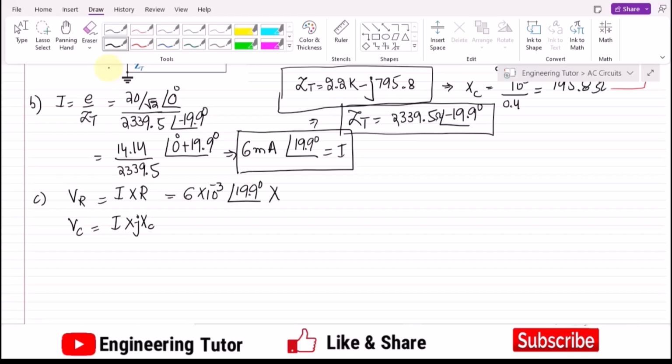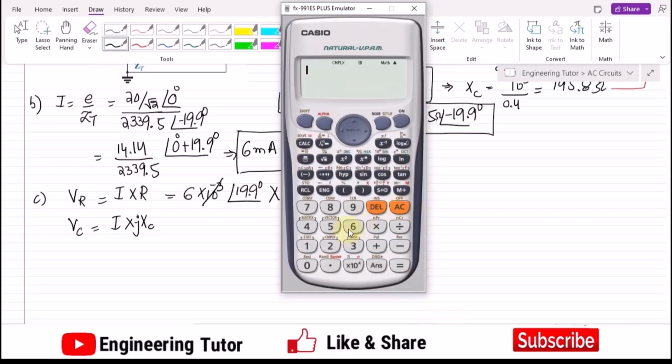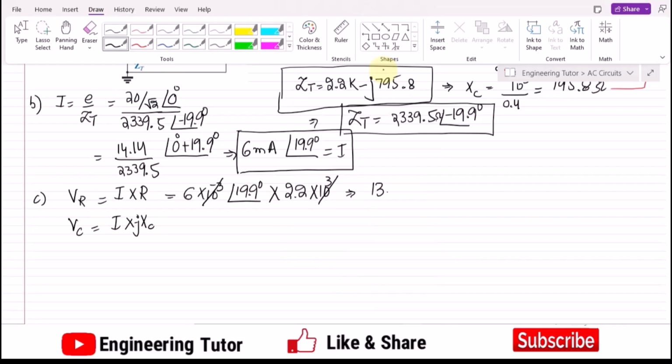The value of the impedance was basically 2.2 times 10 to the power 3, which was the resistor. So these two will cancel out, and what I will get here, 6 multiplied by 2.2 is how much? 6 multiplied by 2.2 is 13.2. So 13.2 volts, and the phase angle it has is 19.9 degrees. This is VR.